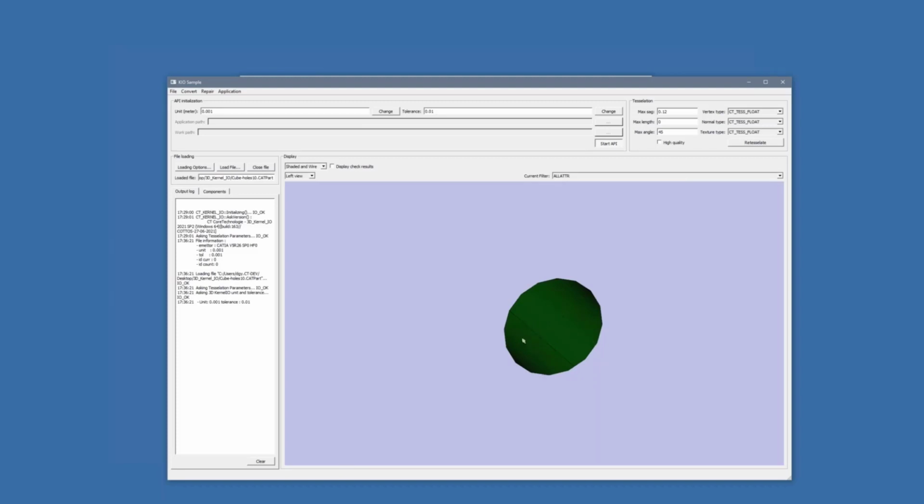and there is a black line of this half cylinder. Now, we have some powerful tessellation algorithms that are able to compute triangles from BREP. And there is something very interesting for most of our customers: we are able to use the topology information to produce a very nice and watertight triangulation.